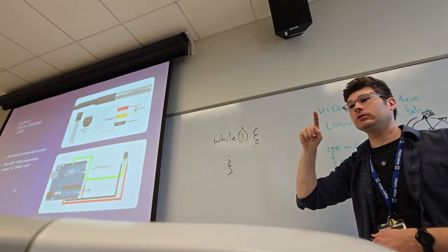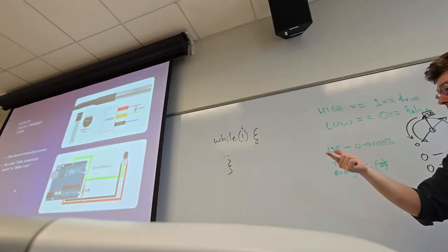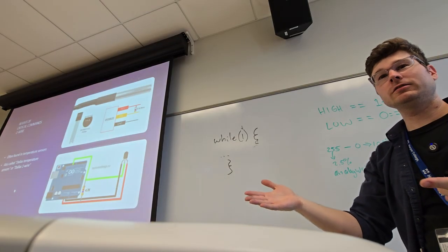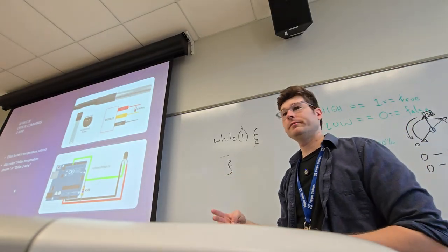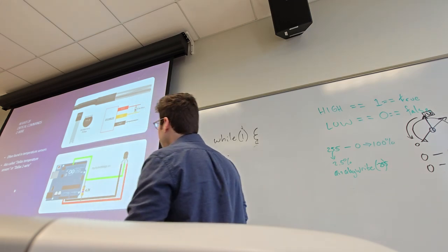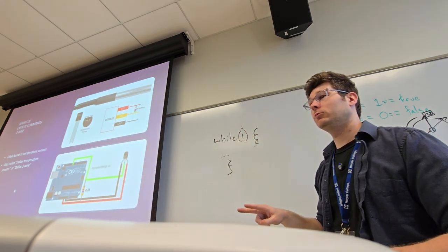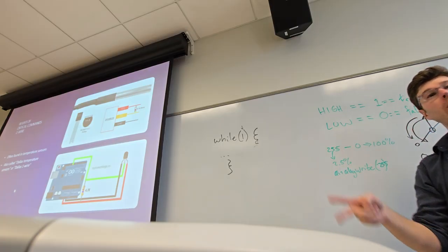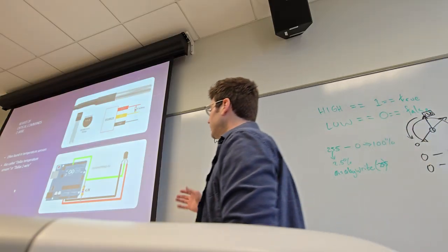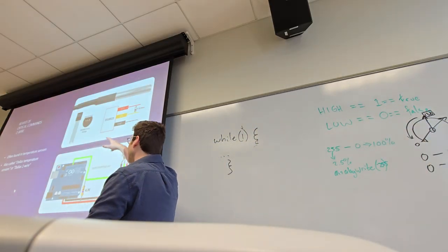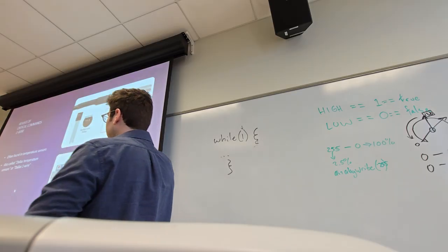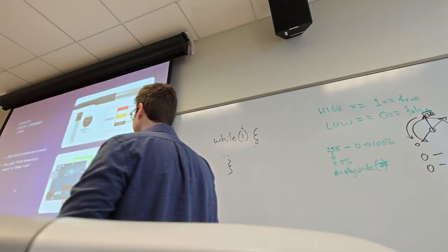Remember, SPI uses MISO, MOSI, SCK, CS, power and ground, 6 wires at least, and 4 for I²C. This guy just needs 3 and only 1 for data. That's its big draw. Some devices can even get away with 2 wires, where 1 wire is ground and the other wire is data that it parasitically draws power through. Kind of cool. But that's its claim to fame, that it only uses 3 wires, and it's called a 1-wire protocol. Also called the Dallas temperature sensors for some reason. I don't know why, maybe that was the name of the company.